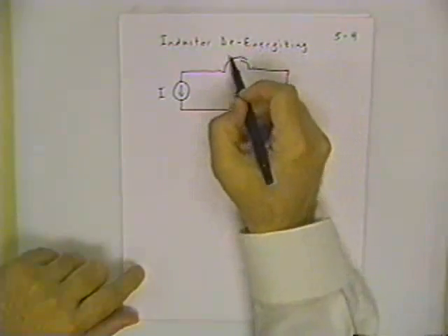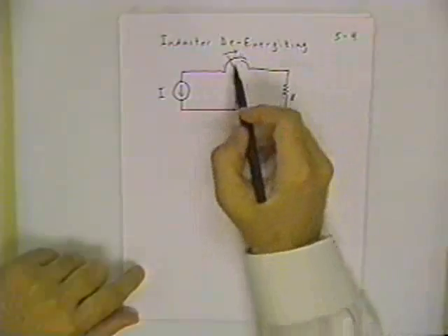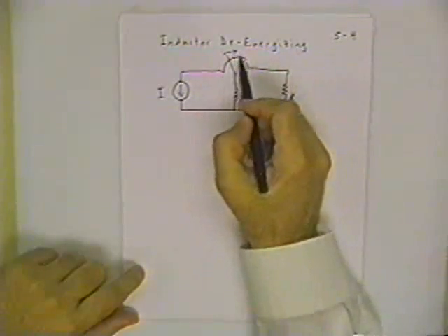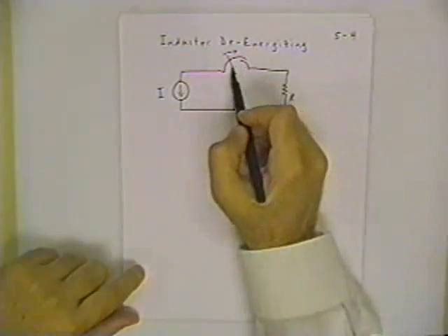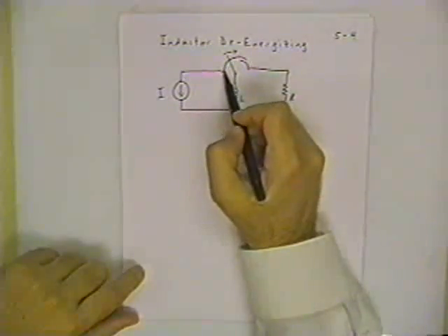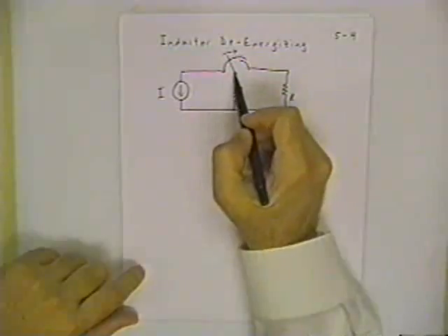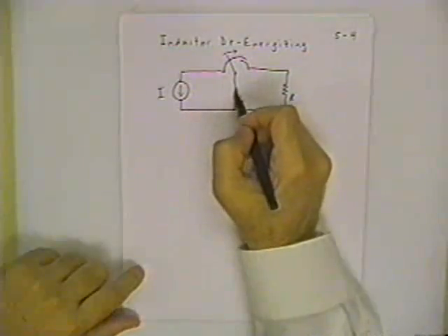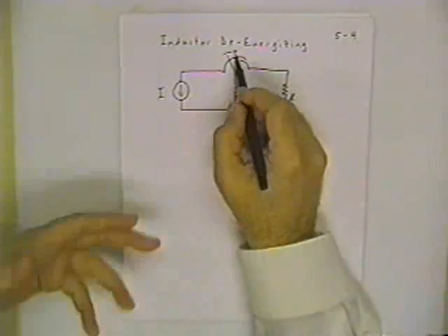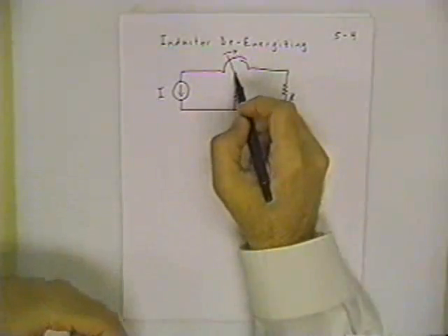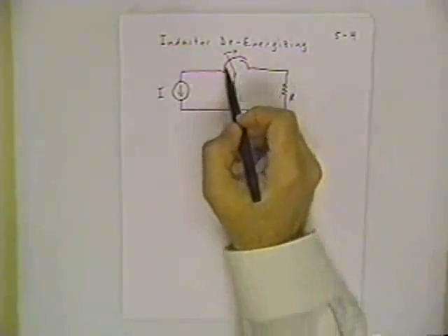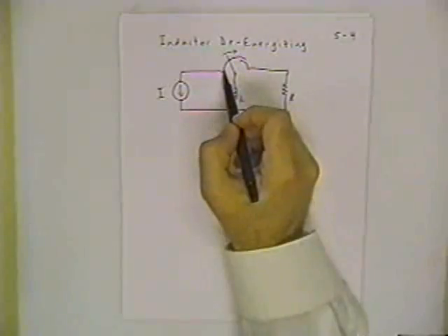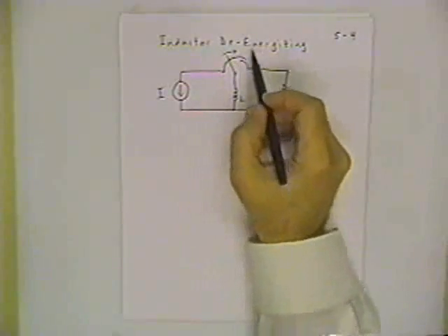It's supposed to indicate that here is the moving element of the switch, and as the switch slides over from this position to this position, there's a continuous contact. If we just used a regular two-pole switch, then there would be an instant of time between the switch in this position and the switch in this position where an energized inductor would have energy stored and no way for that energy to be released in a controlled way. So you'd have tremendous arcing problems, and that's just a safety hazard. So whenever I show this circuit, I always include this sliding contact switch to illustrate.